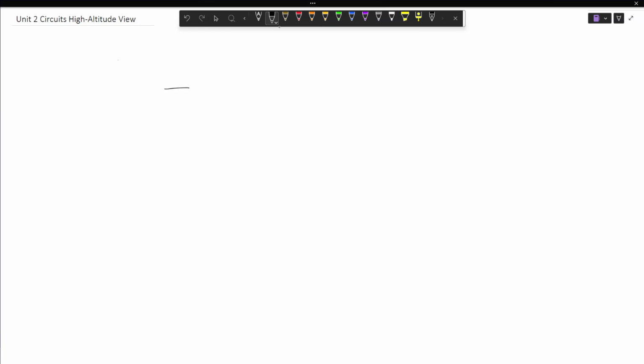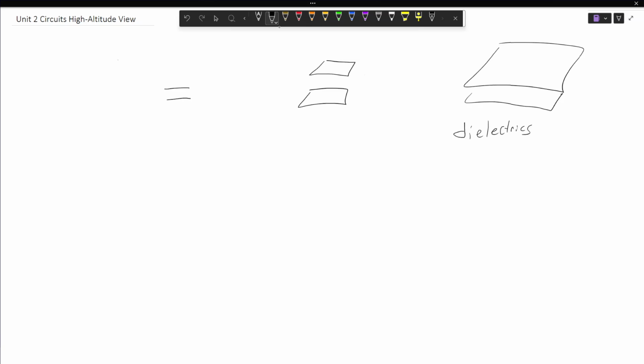So the capacitor, because we tend to think of them as these parallel plates, where in reality they're often these big sheets that we build, oftentimes with something sandwiched between them to prevent the sheets from touching, and to serve another purpose that I'll talk about in a little bit called dielectrics. And of course, as with everything else, we'll really delve into huge detail later on with all of these pieces. So there'd be like this dielectric sandwich of a different material in here. And then we would take this whole thing and roll them up.